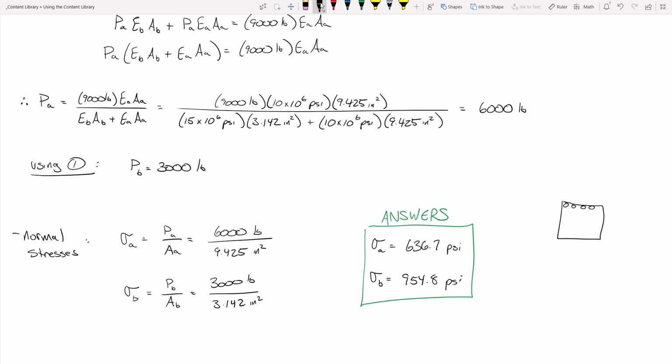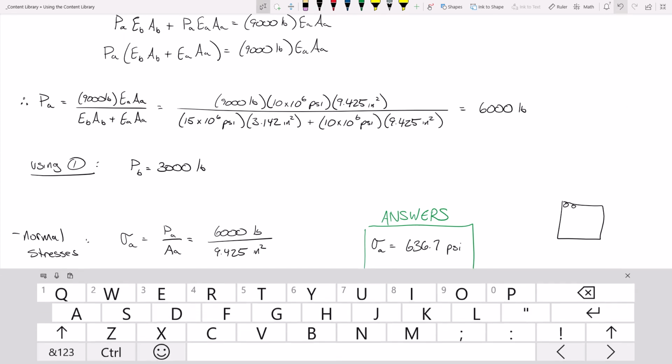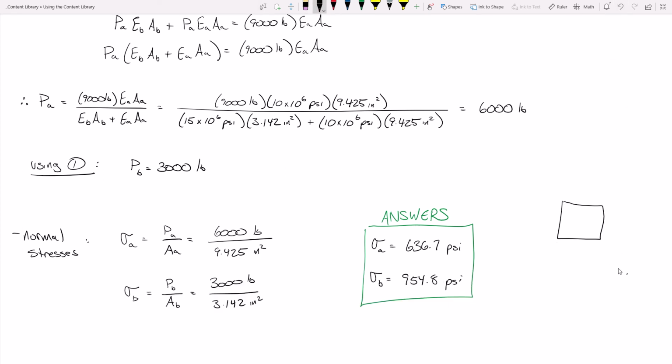Instead, the rebar is going to be inset some. So what it's actually going to look like is like this, okay? And there is some distance here between this and that. There is some prescribed distance, okay? We call that distance cover, okay? Now, the reason for that cover is for environmental protection. It's to prevent against water penetration and corrosion and so on and so forth.